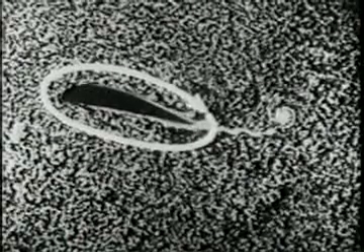This requires, though, that there be along this other curve surrounding the airfoil a circulation equal and opposite to that on the curve surrounding the vortex. This circulation around the airfoil, which may be ascribed to a fictitious vortex bound in the airfoil, is necessary for the production of lift.